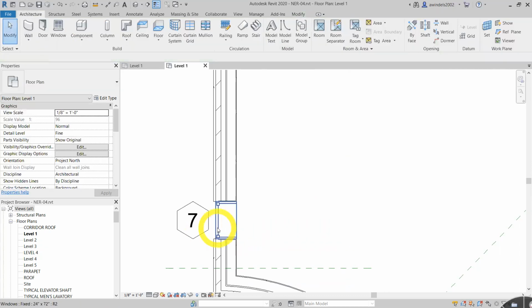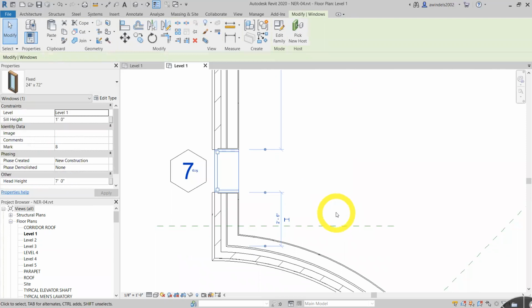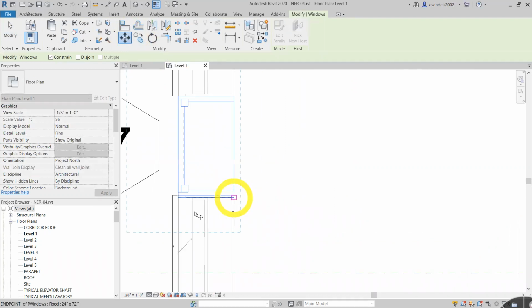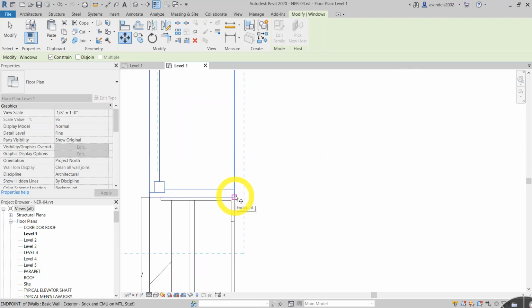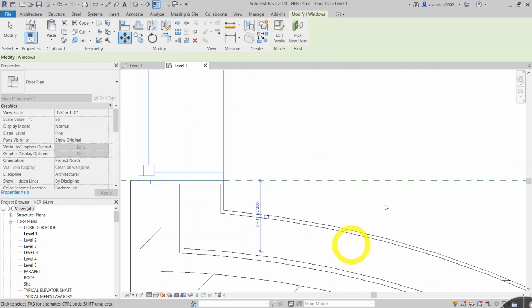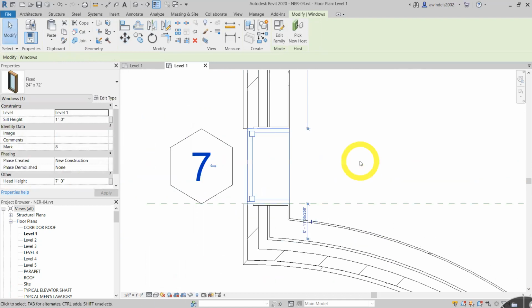Oops, hit escape twice. Let's click the window. Let's check our temporary dimension in this case. Yeah, let's move the window. So this is what it's having us do. We pick the window. We want to move it exactly to the reference plane. So let's go to the move. And if you check your status bar, enter to move to the start point. These commands get pretty repetitive, but you'll get better at them. We'll say, okay, that's my start point. And we'll go to the intersection snap, which is the X. That's my endpoint. So there I move my window exactly where I want it.